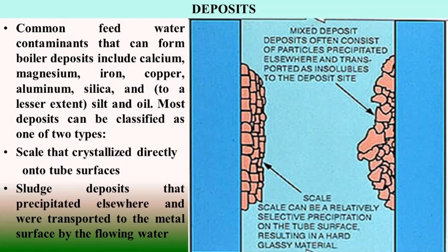Now, carbonate deposit is usually granular and sometimes very porous in nature, and sulfate deposit is much harder and denser than carbonate deposit because the crystals are smaller and cement together tighter, but it is more brittle. Now, silica deposit is very hard, resembling porcelain, and the crystals of silica are extremely small, forming a very dense and impervious scale sometimes found on tube surfaces. These scales are extremely brittle and hard and very difficult to remove.